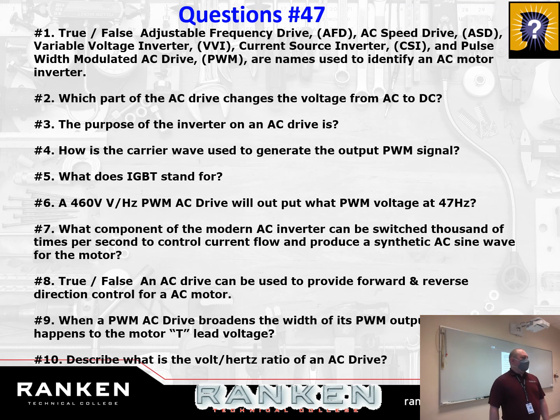What did you have for 6? There's a certain point, though. The drive tops out at max voltage if you go above a certain frequency. Let's say you go all the way up to 100 hertz, but the motor's supposed to be running at 50. At 50 hertz, you get 208 volts. At 100 hertz, you're not going to get 416 volts.